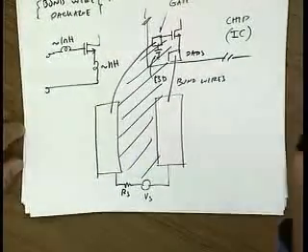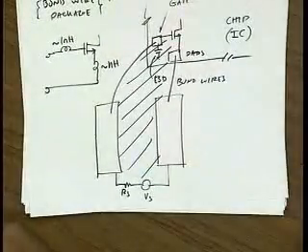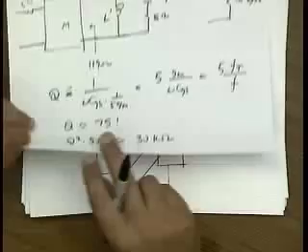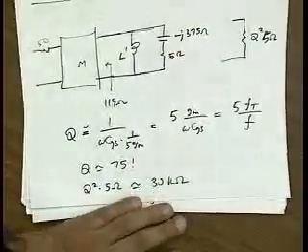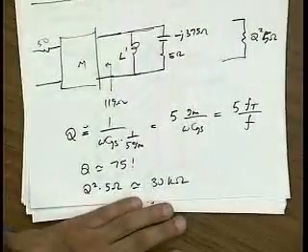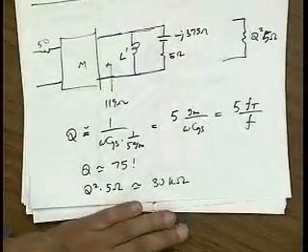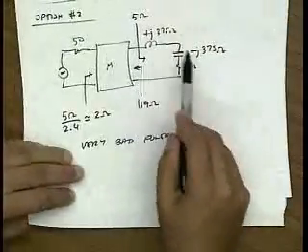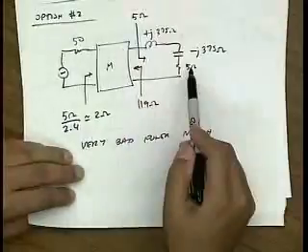Before that, can I ask a question about option 2 and option 3? Sure. Can you combine option 2 and option 3 by inserting a small series inductor with the capacitor and then putting a big inductor in parallel? Yeah, so basically you could do a multi-stage, right? So over here, I can have another matching network to try to match this up.